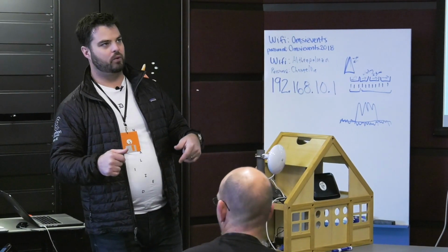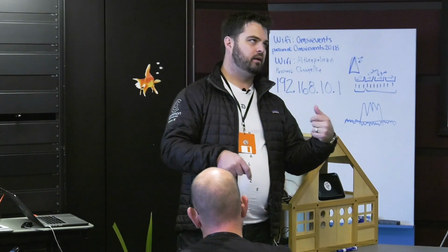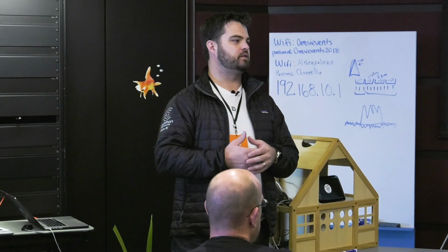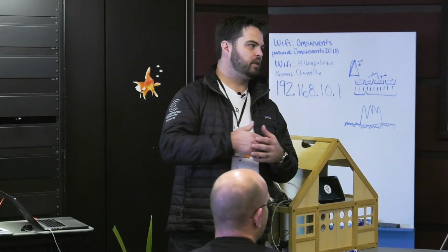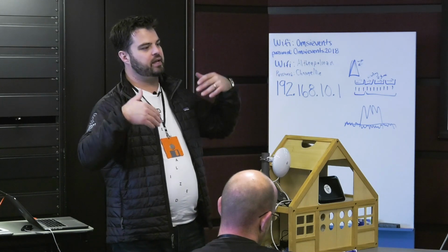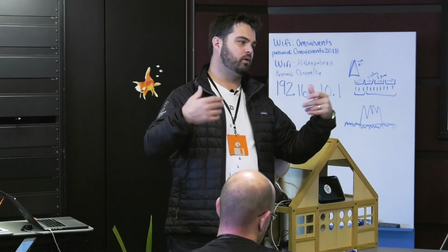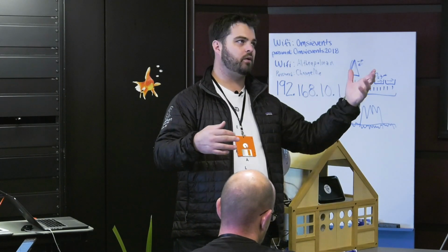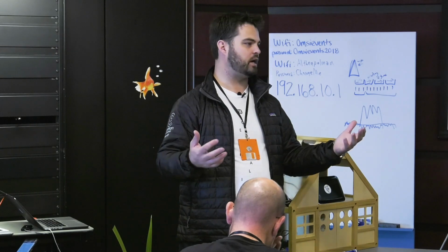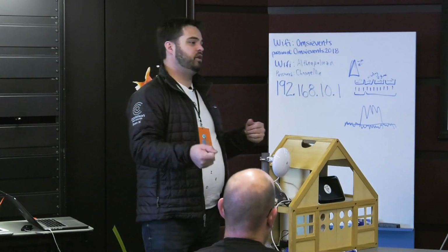When you are leasing a tower from a tower company, they will sometimes require you to have a structural assessment done on the tower. Usually they'll do a structural assessment initially, and as they get closer to having that tower maxed out, they will require new entrants to have a new structural analysis done to make sure that their equipment won't overload the tower. Again, that's something that should really be done by a professional engineering firm.